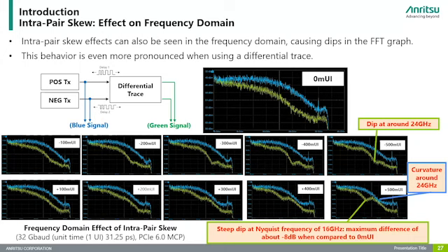This is very interesting data from an actual measurement. Now, give a skew between P and N through the differential pair trace. The blue trace is the input of the trace, and the green trace is the output of the differential pair trace. When you have no skew, of course, there is only ISI channel loss, so you can see a very smooth trace. Now, increasing the